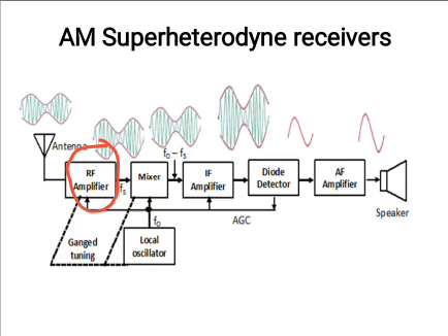This radio frequency amplifier can be tuned to select and amplify the particular frequency within the AM broadcast range. Only the selected frequency and its two side bands are allowed to pass through the amplifier. Next, the high frequency signal of the received signal is called the radio frequency signal and its frequency is the radio frequency Fs, and the local oscillator signal operates at F0.